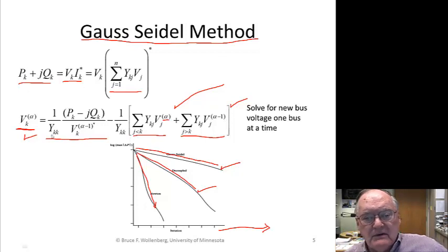That can be executed fairly quickly because it doesn't have any matrices to do, and then switch into the full Newton or the decoupled, because that gives it a good starting point. It's a good way to start the calculation off, rather than the Newton where you may take such a big step, and the first condition on the system may not give you a good place to start from, whereas 10 or 20 iterations of the Gauss-Seidel will.